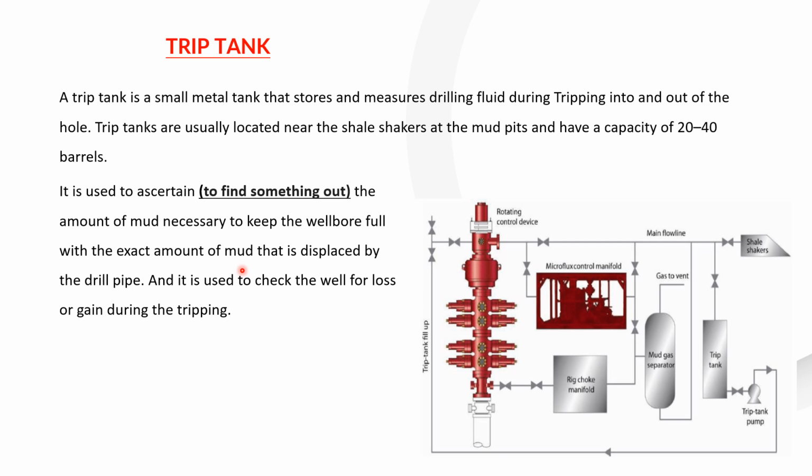If the hydrostatic pressure is less and the formation pressure is more, then there will be a kick, and if the kick is not controlled, then it will turn into a catastrophic and uncontrollable blowout. And if the blowout has already come, then it means that everything is finished. Okay, so